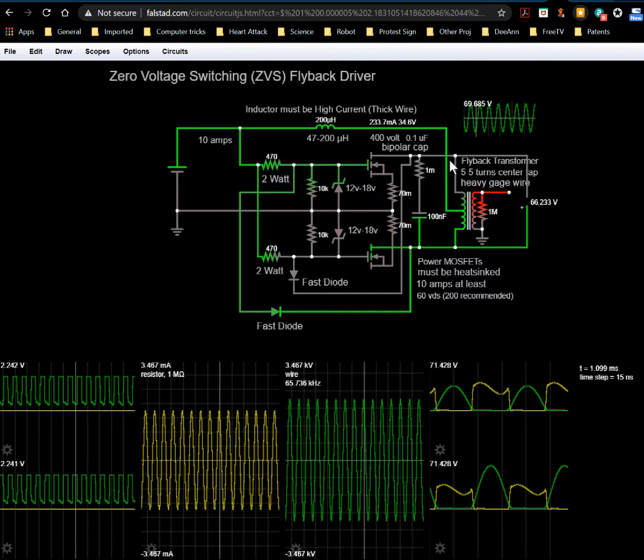But let's see, you got current flowing through this, because this one just arbitrarily happens to be the first one that turns on. When this is on, this is off. And when this is on, this is off. Both of these cannot be on at the same time, by any stretch of the imagination. And both of these cannot be off. They're mutually exclusive. They can't be off at the same time or on at the same time, because when this is on, okay, that makes this voltage low, which allows current to flow through this diode to ground, which does what to this voltage at the gate?